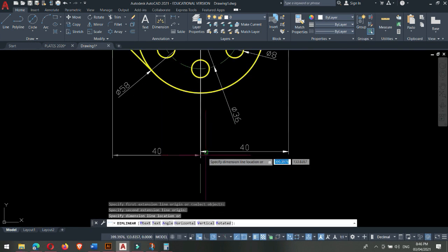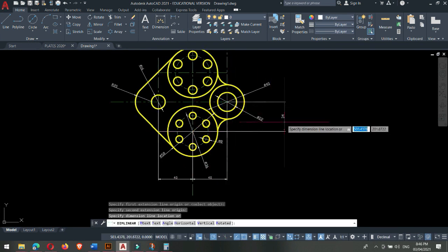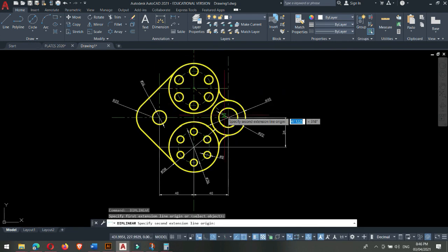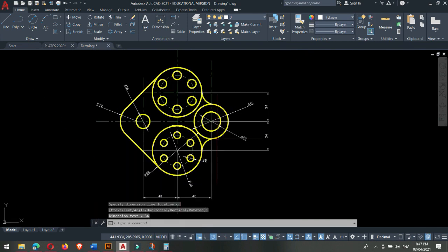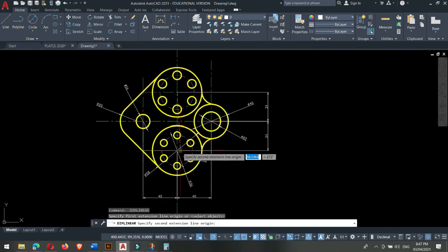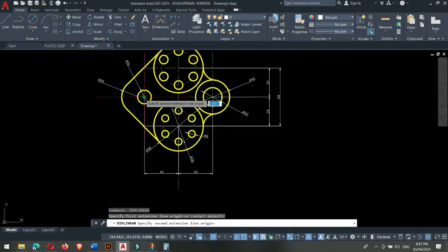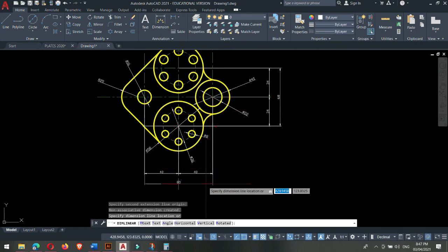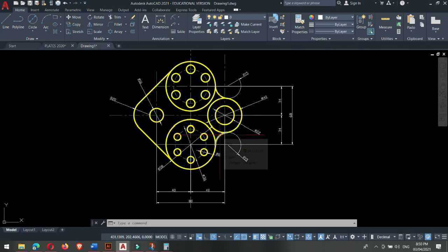Alright, going down here. If AutoCAD gives you another dimension rather than 34 or 40, that means that you have created a short distance or a long distance circle. It depends. So make sure that every time you do a certain object, you put dimensions so it is accurate. Okay, so what else? There's actually a radius here, 15. Down here, 15.